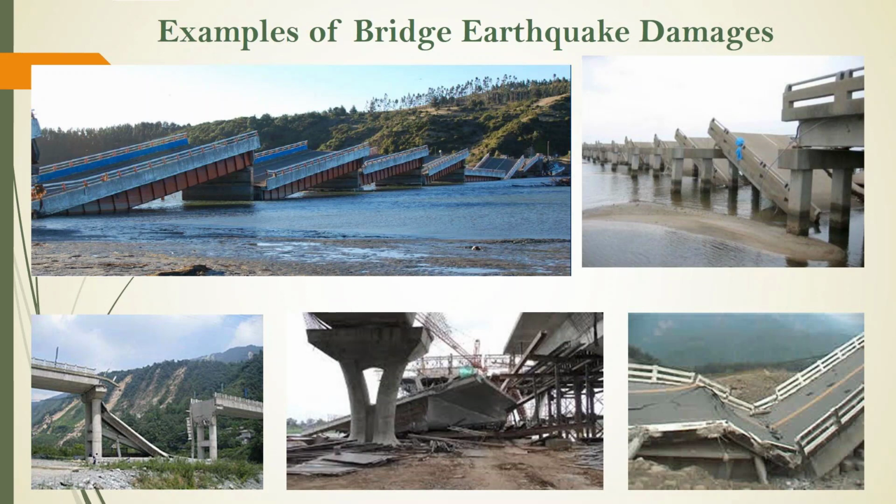This picture just shows why we are doing that, because seismic design is essential for bridges. It is an extreme event, doesn't happen every day, but when it happens, we have to be ready for that. So continuity in the superstructure is very important. Good foundation design, good joint design, shear design, and overall structural behavior ensure that we have a consistent load path from the super to sub to resist the earthquake.